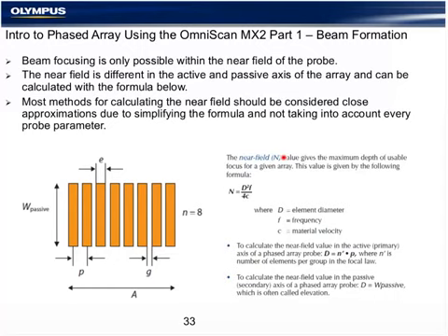In many of our applications, like ASME weld inspection of new construction, the reject rate is designed to be compared to side drilled holes or notches in calibration samples. To have a phased array inspection generate the same reject rate, you would need to use an unfocused probe by entering a number larger than the near field.